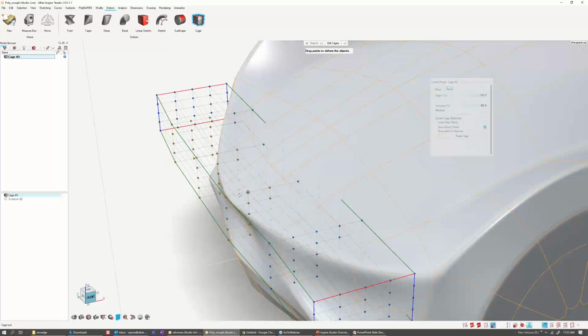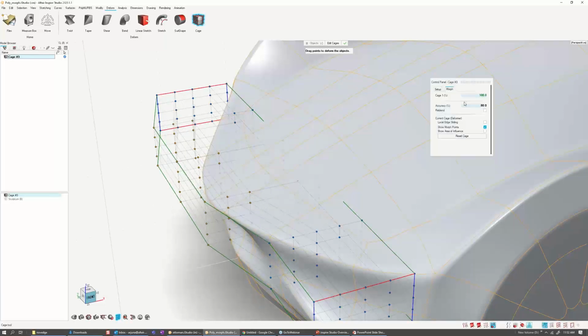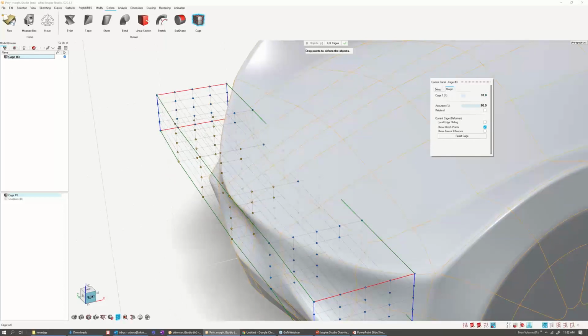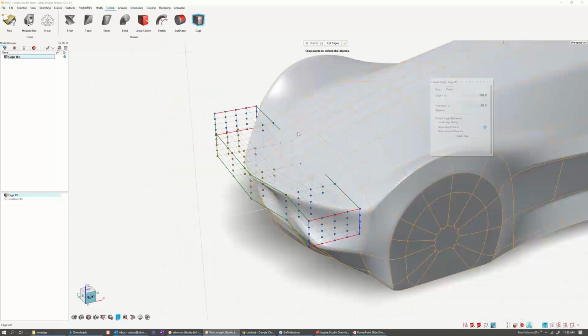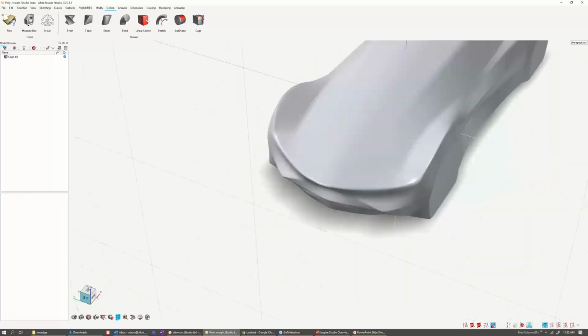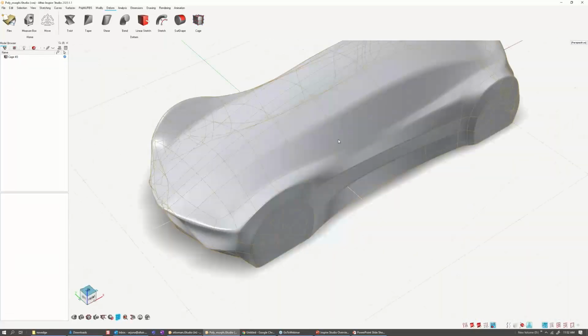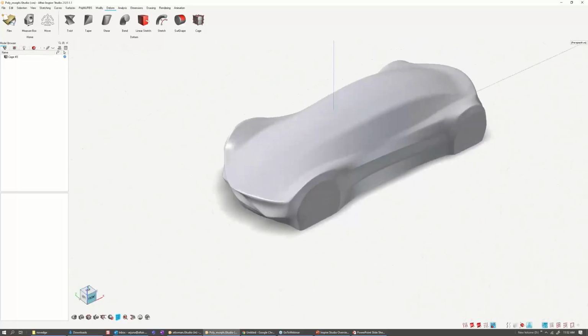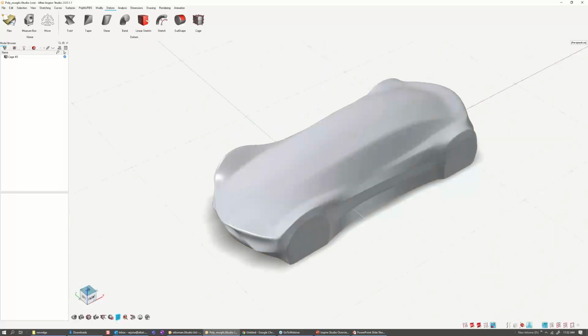morph. So I can move it here, and I can see how much effect this morphing has on my underlying cage. So I can change it from 0 to 100. So this way you can add many cages around the object, and this can be applied to almost any object. And I think in the upcoming webinars, I will cover some more in-depth cage tutorials, in the sense that I'll show you some simpler objects that can definitely benefit from the cage.